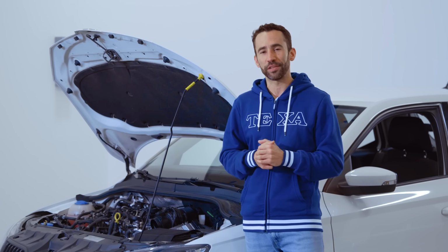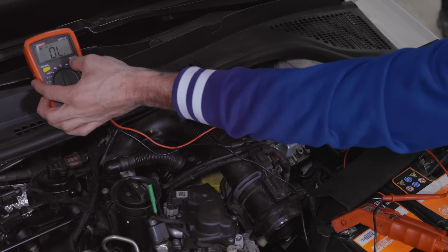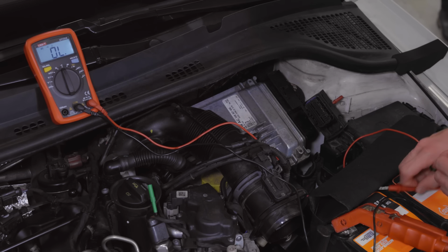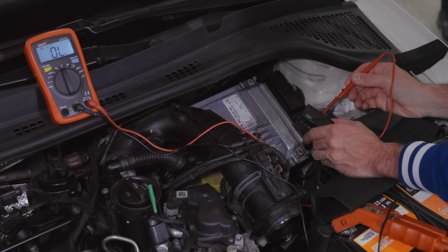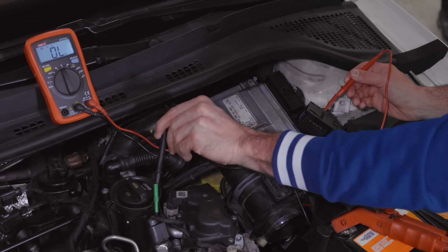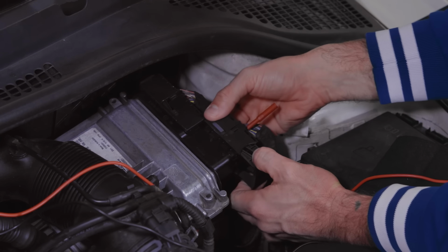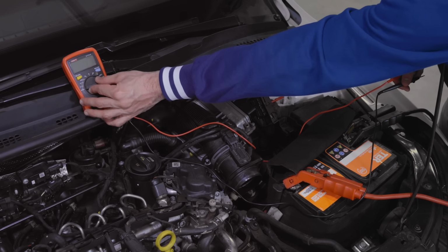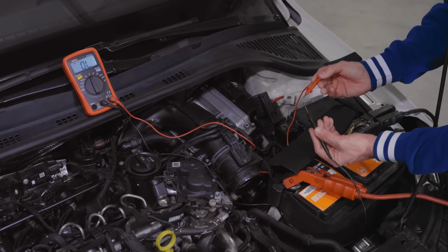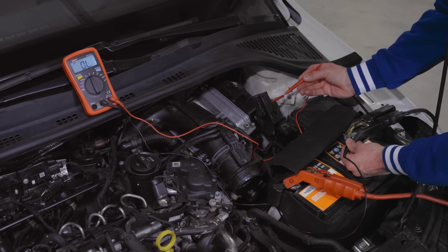Let's start with the outage theory. To understand where the problem is, we have to check the continuity between pin 3 on the fuel pressure sensor and pin B51 on the control unit. Using the multimeter, we found that the line is conducting. Therefore, there is no outage. Let's pass on to the second theory and check for the possible short circuit between the power line and the ground. We have found the problem. The 5-volt positive line is short-circuited to ground.